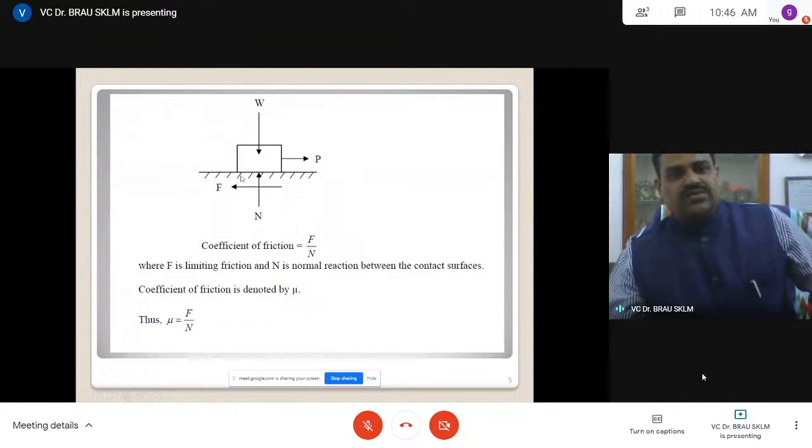From these two you can determine the resultant, because these two are perpendicular. The resultant and this force, then the three forces are concurrent, and they must be in equilibrium. Draw a polygon or use a geometric method like Lami's theorem, or analytical methods: sum of the forces in x direction is 0, sum of the forces in y direction is 0.